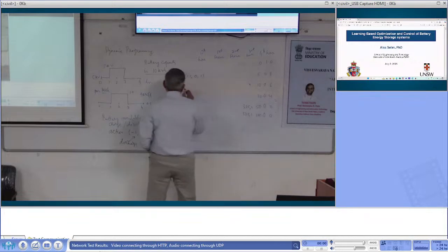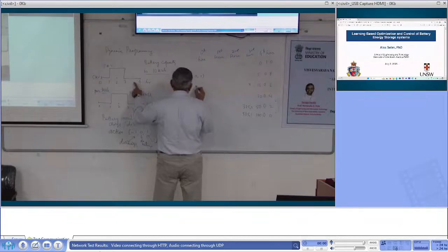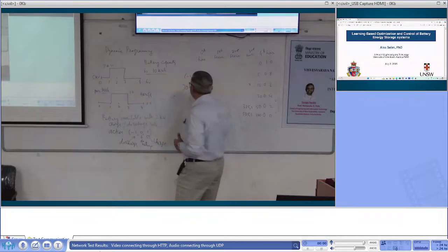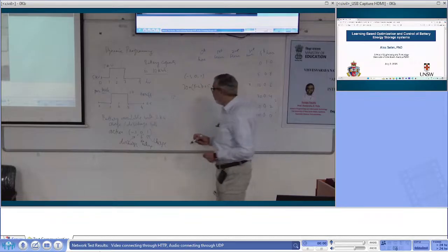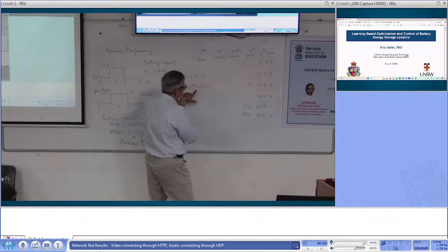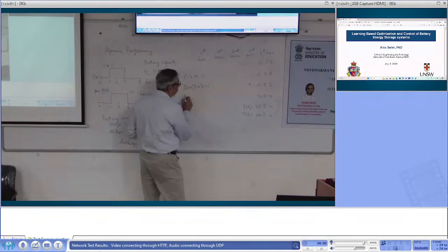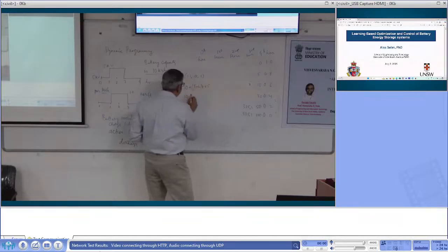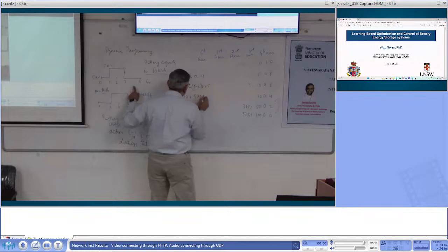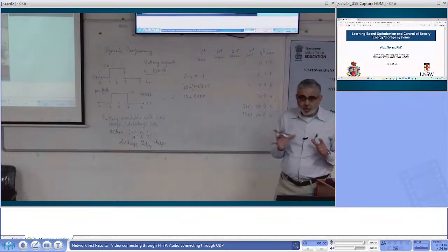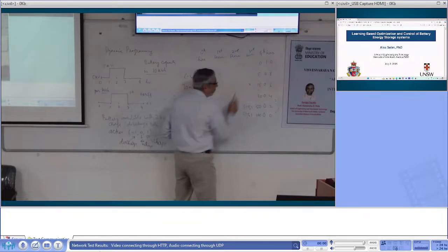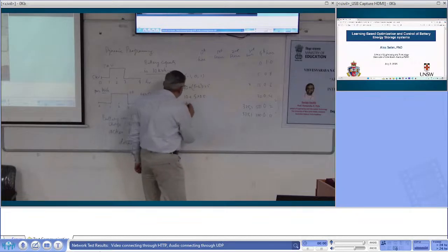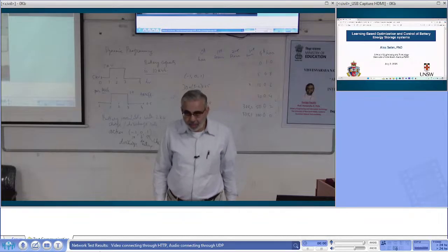Okay, so 30 plus load is 5 and I am discharging the battery, so -2, because load 5 times tariff is 0.5. Then the second thing is I am doing nothing. If I do nothing, cost is 10 plus 5 times 0.5, because there is no battery, load is 5. Now the third thing is I charge. If I charge, I end up there. So cost is 5 plus 2 times 0.5. So we have 3 numbers.